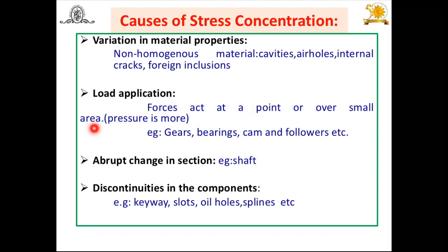That means while calculating the stresses using the elementary equation we consider a small area, but at that time you will find the pressure is more, in gears, in cam and followers, and in ball bearings also. Because of this there is stress concentration at the localized area where this point load acts. That's why load application is another cause of stress concentration.